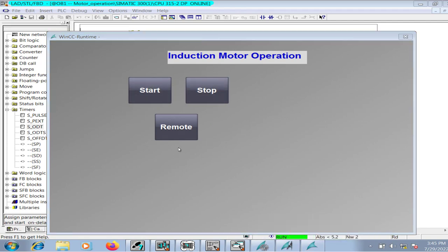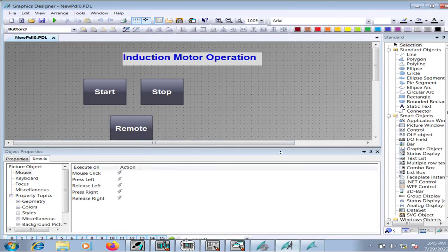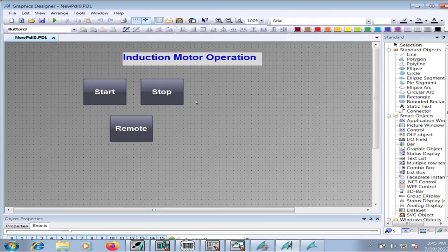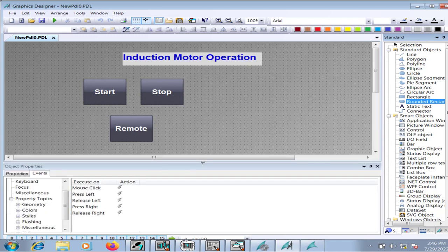Now let us make some additional modifications to my graphics HMI. I will store the status on the HMI. For example, ready signal, run fault, overload, local start and local stop command. And I will also add the motor graphics onto the HMI.